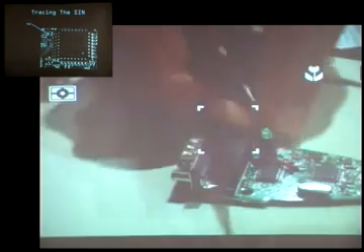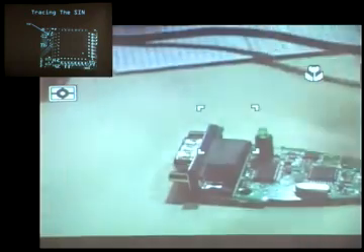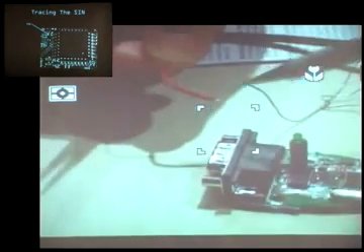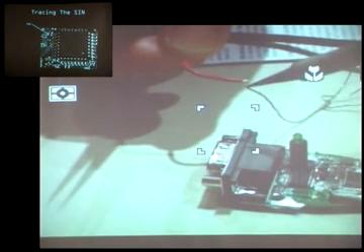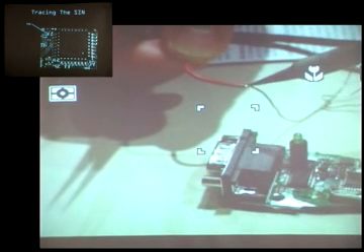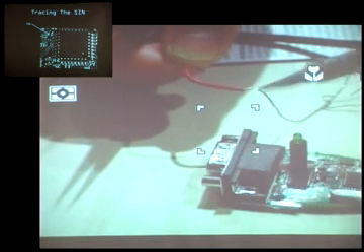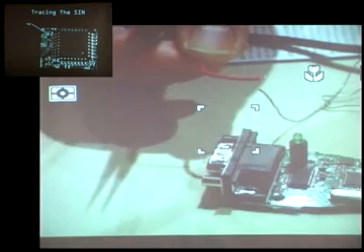Now I'm going to take this wire here, and I'm going to put a bead of solder on the end. And that's going to be the bead of solder that's going to be heated up and it's going to make the connection to the pin. So I'm just going to go ahead and take this and sort of add a bead of solder to it. Okay. So now I've got a little bead of solder right in the end.